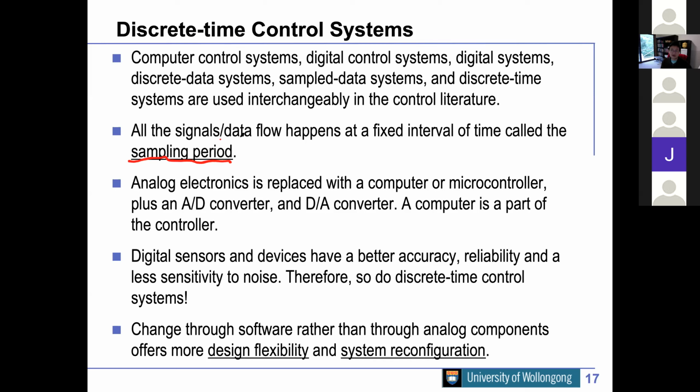If you have a high enough sampling rate, and if your analog to digital converter has enough bits, so you have enough accuracy of the measurements, and those two things are much higher than what your system requires, then pretty much you can use classic control theory to do digital control. You don't have to learn a new bunch of theory.